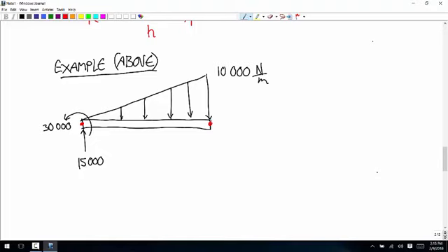There is a point couple and a point force, but those both are at the same point, and we've already dealt with that point. So we don't have to deal with that point again. Is there anywhere else where any of that's happening? No. So we only have 2 of these points where the subfunction can change. And so we have 2 minus 1 cut that we have to do. So this 1 cut is going to represent the whole beam.